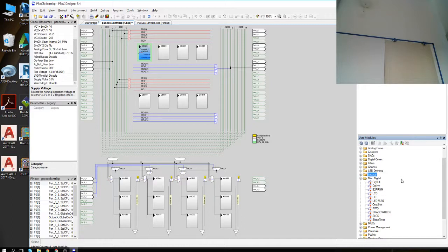Okay, shadow registers. Are you familiar with shadow registers? That's a good trick if you want to, for example, invert an LED, and the LED, for some reason, doesn't have a big enough resistor there. For example, you want to run it at full tilt what the processor gives, but it might be that you don't get the output voltage of that pin high enough to be logic state 1.